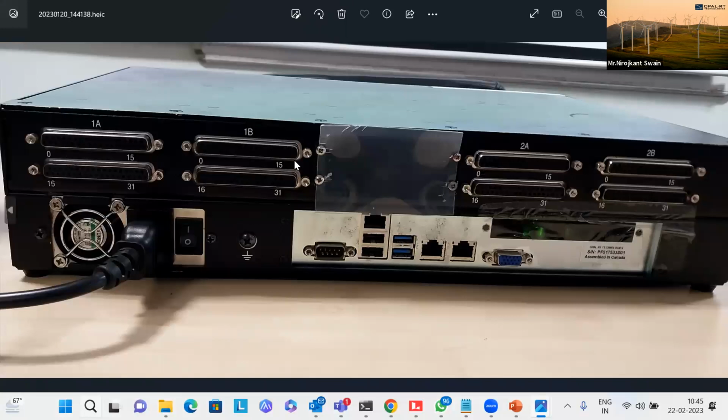Just ignore this IO card for now. We'll explain it in the afternoon session. And this is your Ethernet port that we call NC1, NC2, Ethernet 0, Ethernet 1. We need to connect from here to your host PC. If you want to use this simulator on a network, you can connect this port to your network, and take an Ethernet cable from your network to your host PC. That we call network communication, and this direct connection to your host PC we call one-to-one communication.